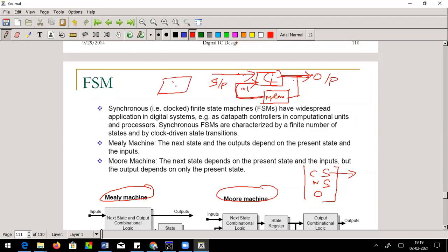If it is a combo logic, the output simply depends only on the present input. It need not think about what was before. Suppose I'm asking you to add 3 plus 5. Will you ask what the previous input was? Definitely you won't ask. You will simply say 3 plus 5 is 8. And the other way, I'm asking about a counter counting the total number of people who have already entered. So I'm asking what the next count is. Then immediately you will ask me what the present count is. Already it is 5.